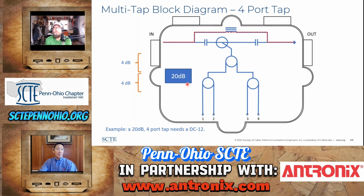So in this 20 dB tap, you would need a 12 dB directional coupler because you have 8 dB of loss through the splitters. So if you want 20 dB from here, 8 dB is lost through the splitters. You'll need another 12 dB through the directional coupler. So this tap has a 12 dB directional coupler to make a 20 dB tap.